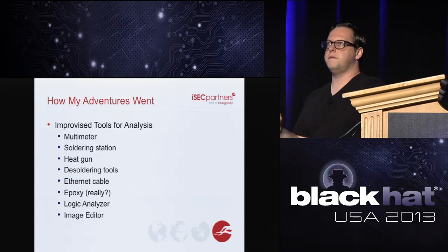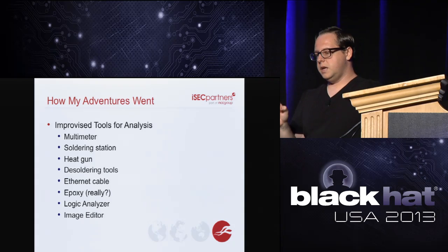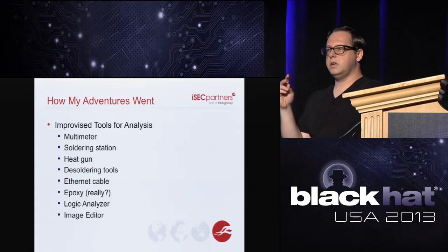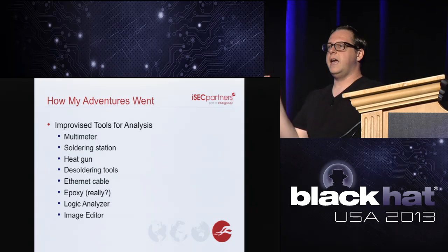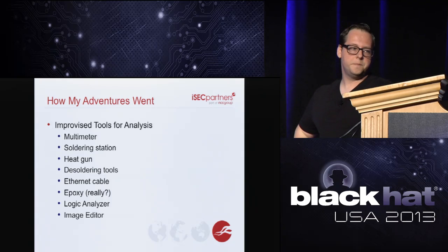The other thing, as we'll see a little later, if the wires are made up of strands, you can take a strand out, cut it, and actually solder it into those vias that we talked about earlier and start sniffing some of the traffic on there.